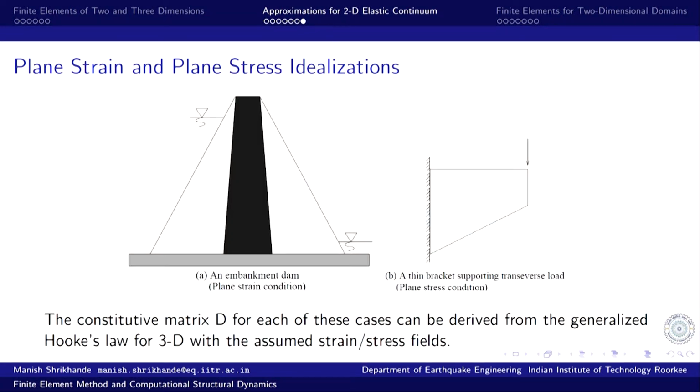I mean, using the plane strain condition, the advantage, why do we need to go into this supposedly unnecessary idealization, because it is an idealization. At the end of the day, epsilon zz is never 0, right, gamma xz, gamma yz is never 0, but we still assume them to be 0 because there is something called the curse of dimensionality.